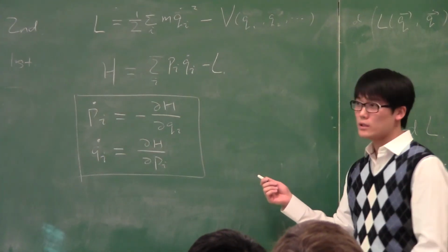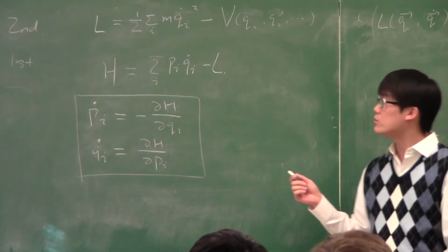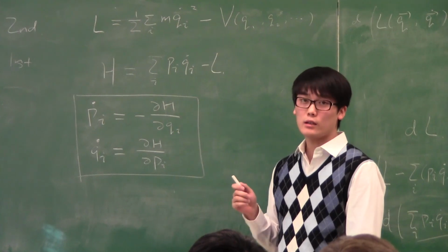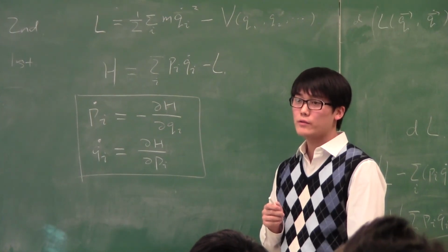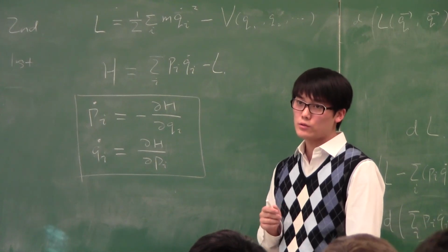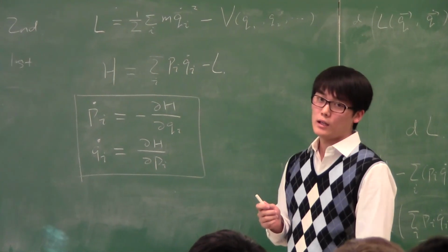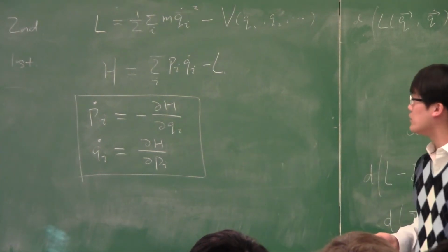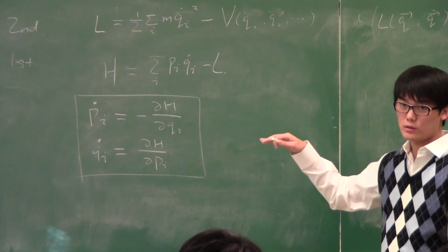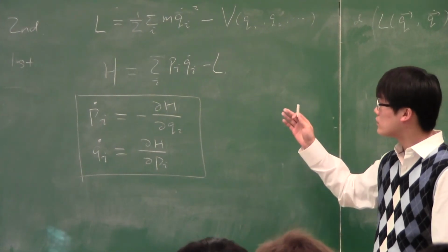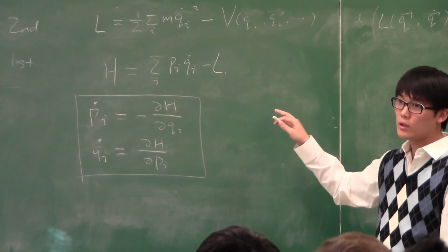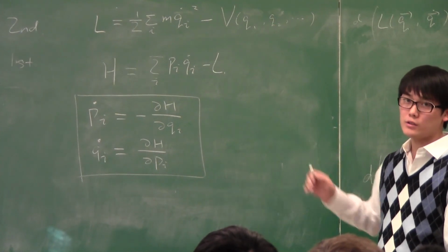But in the Lagrangian and Hamiltonian formulation, these two scalars that correspond to the kinetic and potential energies, often it is quite simple to make an educated guess as to their form. So it's quite easy to write down T and V. And so once you've written down T and V, once you know the Hamiltonian or the Lagrangian, then deriving the equation of motion is almost a mechanical exercise. So the problem remains doable in the Lagrangian and Hamiltonian formulation for quite large systems.